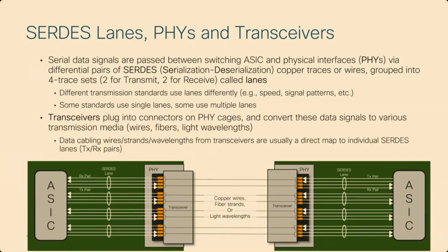When I'm plugging in a transceiver, I am taking the electrical signals that are coming from the switching ASIC on the system board, going to the physical cage for that transceiver, and I am picking those signals up, and I am translating them, usually to a different type of signal that is going to be sent over an optical connection, or potentially a copper connection as well.